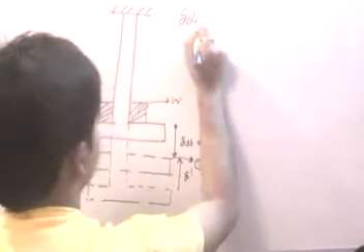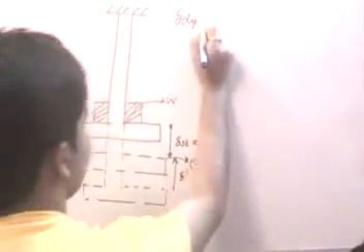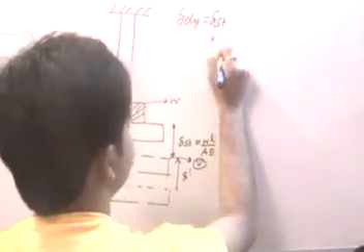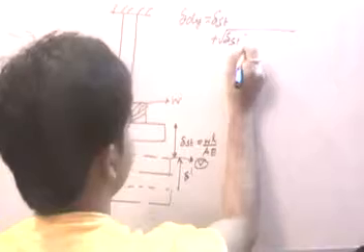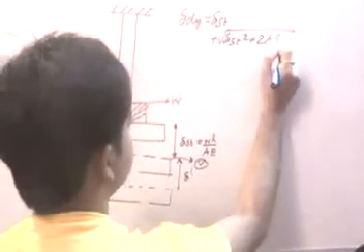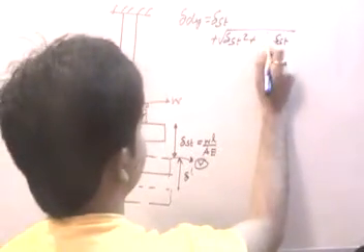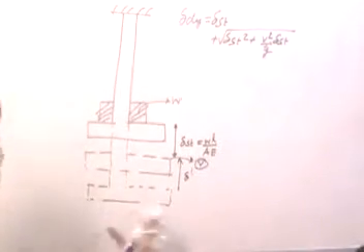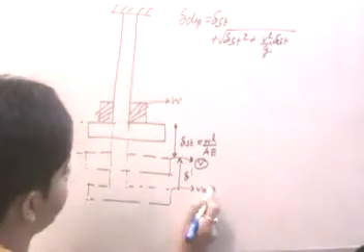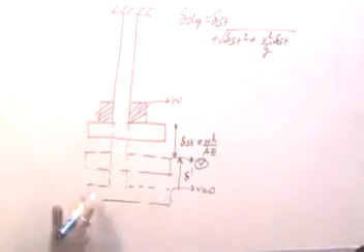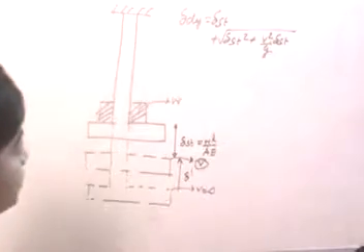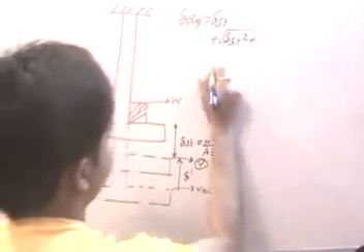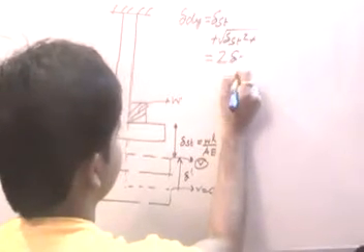Now we know that delta dy, so this is a case of dynamic loading, and we know that delta dy is essentially equal to delta St plus square root of delta St whole squared plus 2h into delta St, or I should write it in the form of V squared by G. So at this point, essentially the velocity will be 0, because this point corresponds to the position of equilibrium. So at this point velocity will be essentially 0, and I can rub this factor out. So if I sum it up, it will be equal to 2 delta St.